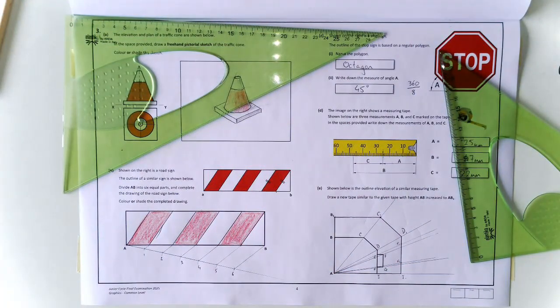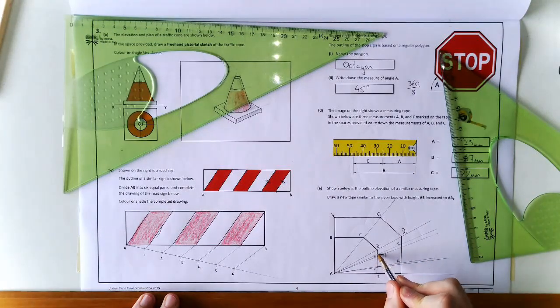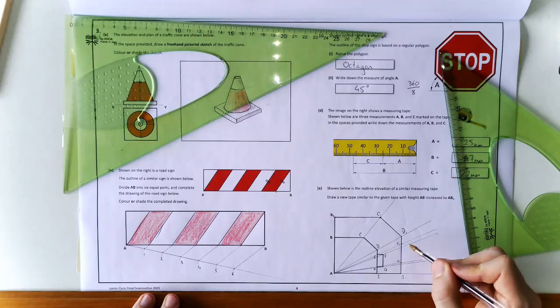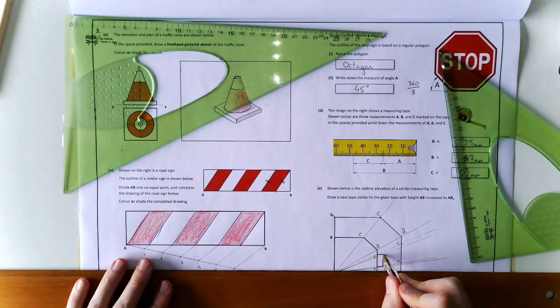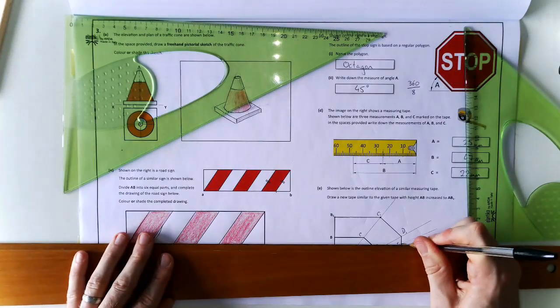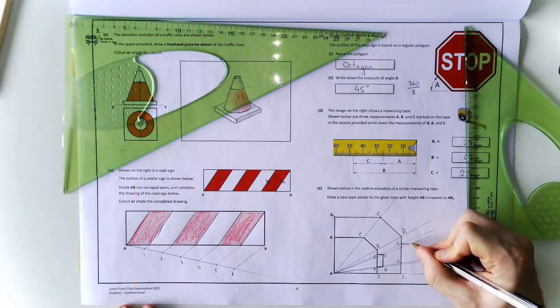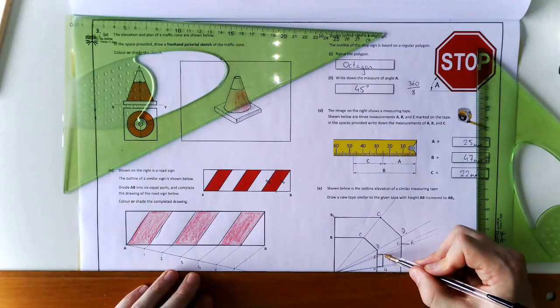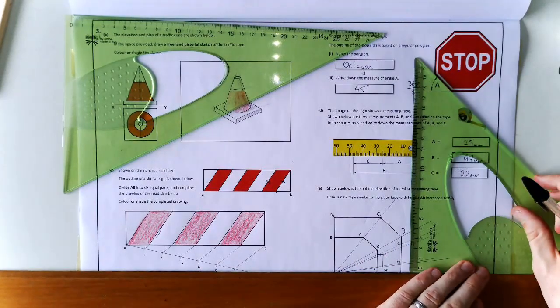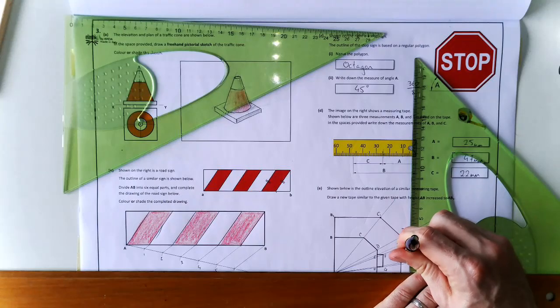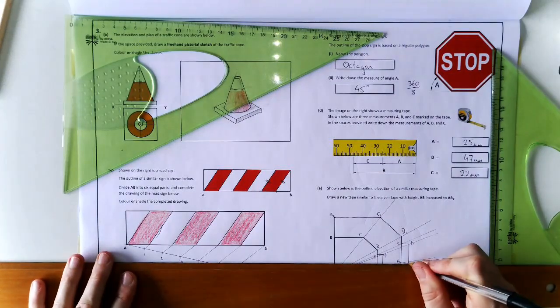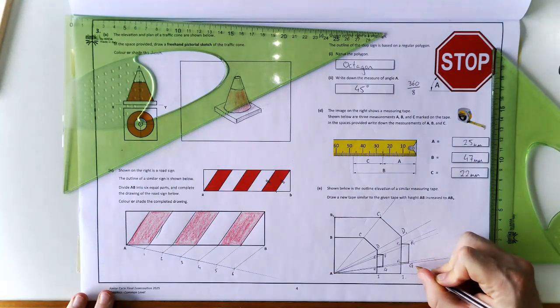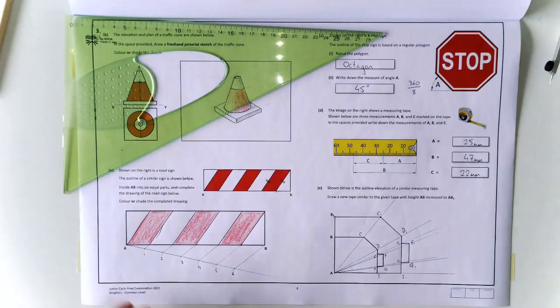All right, and lastly now we need to find F and G. So we have point E right there, where it's radiated out. And we're going to go parallel up there like so, and that will find me F1. I can go straight down then to find G. So parallel to FG, I'm finding F1, G1. Down onto its radiated line, and I can go horizontally back then. So that's G1.